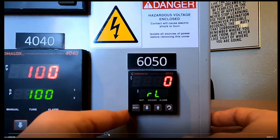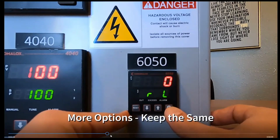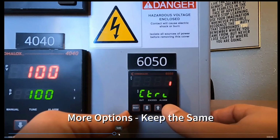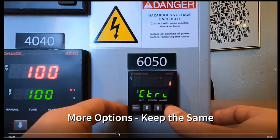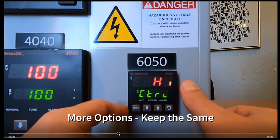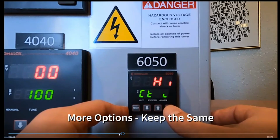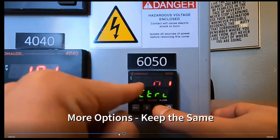Okay, next one is going to be, there you go. So offset, again, we talked about that before. We're not really going to need the offset too much on overtemps because, quite frankly, they'll be attached to the heating element. Yep. So this is working with a high limit or a low limit. These are over temperature controllers. We work with heaters, so we're going to use high limit here.